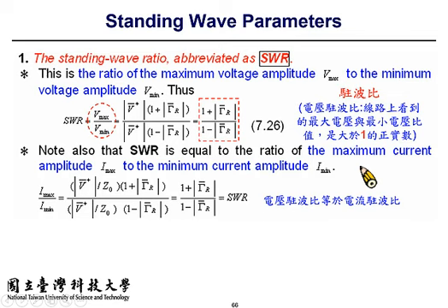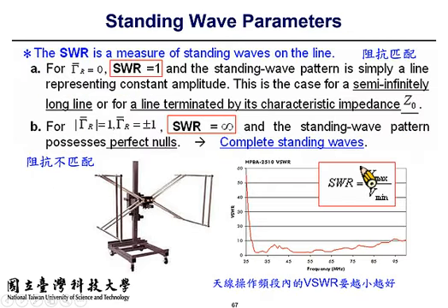Now this result only reveals half of the characteristics of the reflection coefficient, because you only have the magnitude information. To have a complete description of a complex number, you need to have the magnitude as well as the phase of the vector. Of course we will need to perform additional tests to find the phase of the reflection coefficient.